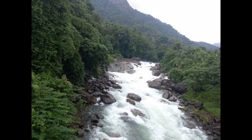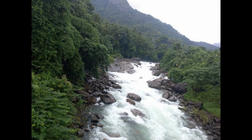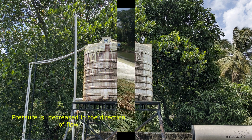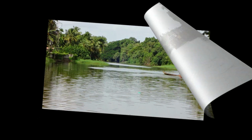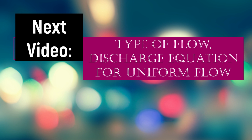In this class we have discussed the difference between pipe flow and open channel flow. In pipe flow, the flow takes place under pressure and the pressure decreases in the direction of the flow, whereas in open channel, water flows with a free surface and the flow takes place at the expense of potential energy. Different shapes of channels are available, so we should know the geometric elements and geometric parameters for each shape for analyzing the flow characteristics. In the next section, I am going to discuss